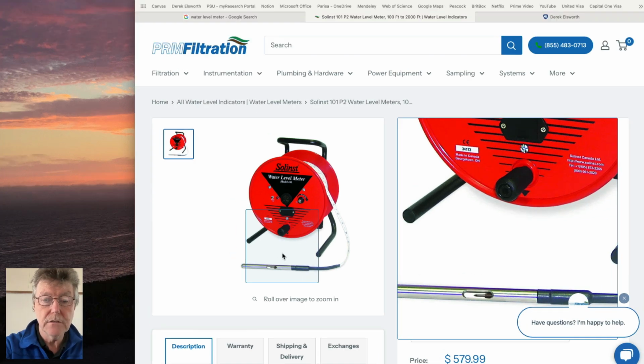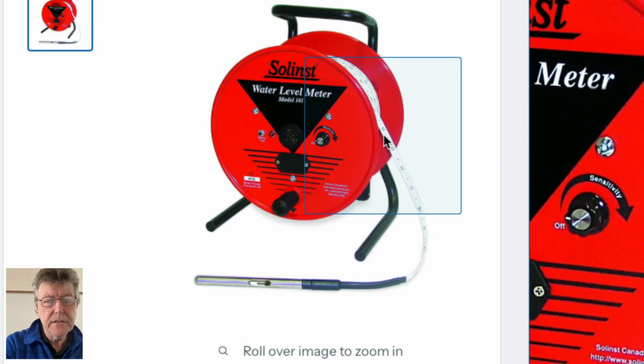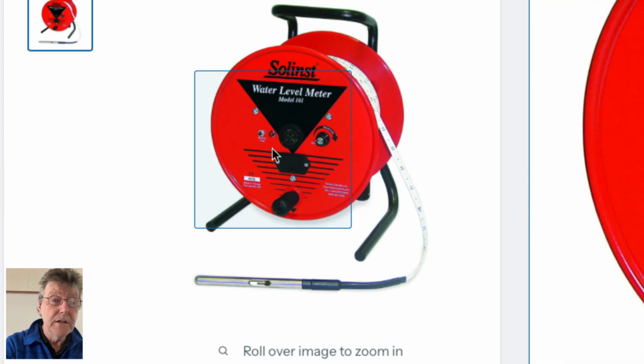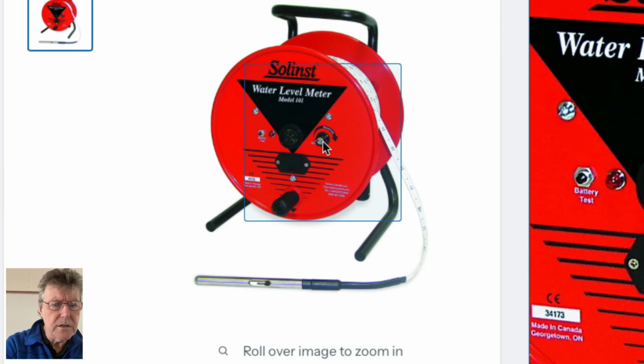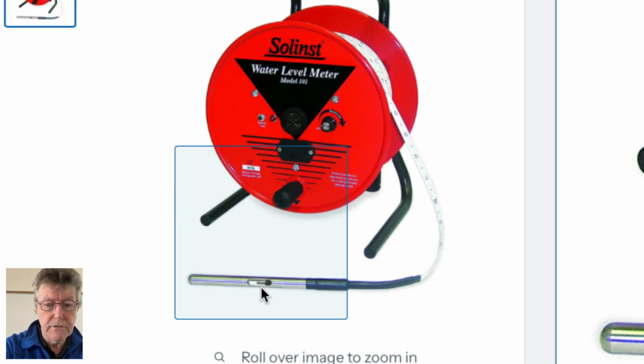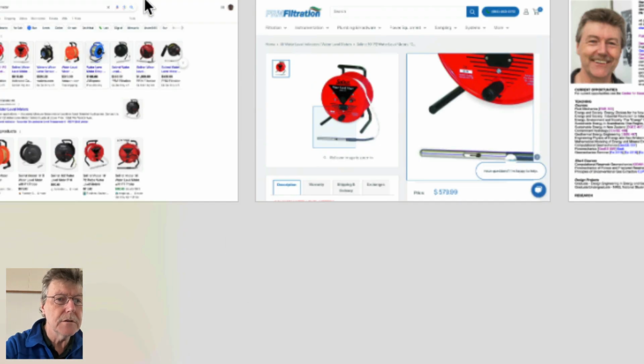The idea is that this spool has a graduated tape. The tape has two conductors going down, which connect with a battery that goes in here and through a circuit with a light, or perhaps a ringer, that you can turn on or off. One wire goes to the outer casing, the other wire goes to this probe in the interior. When you hit water at this level here, it makes a circuit, connecting the interior probe and the outer casing, and the light goes on. Did I switch pages perhaps or something?